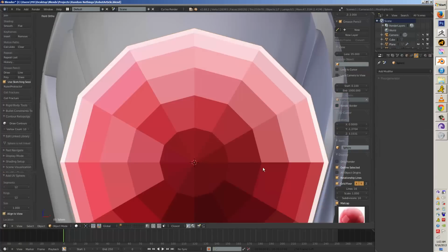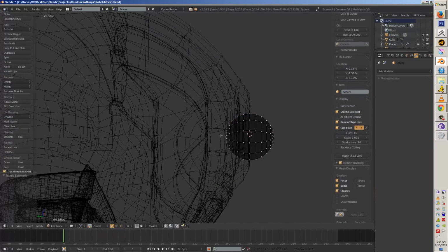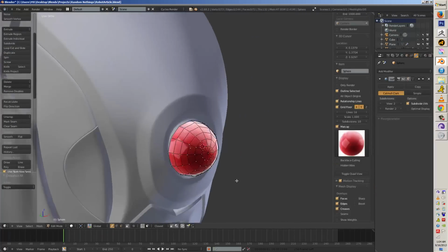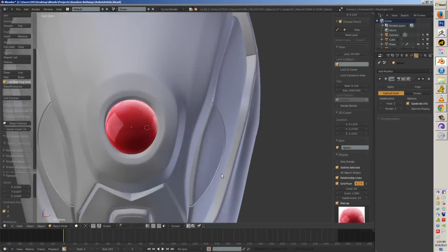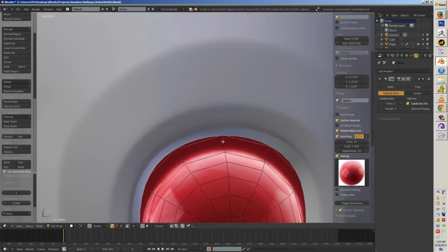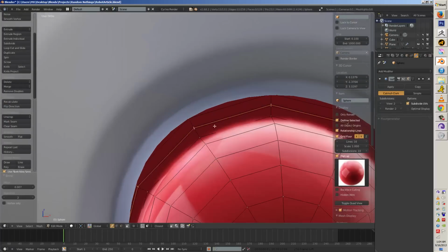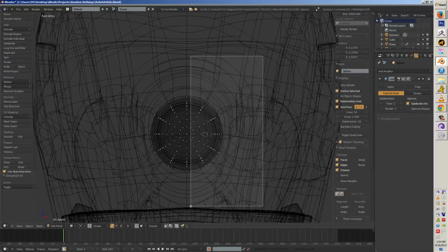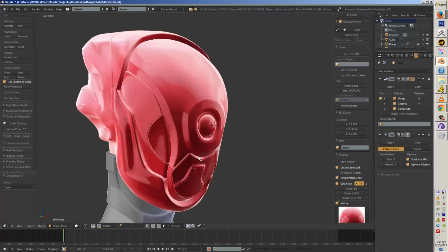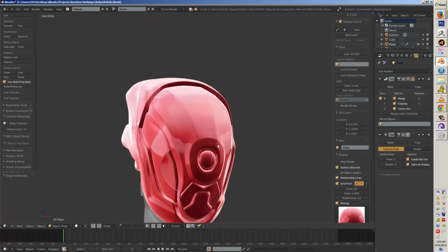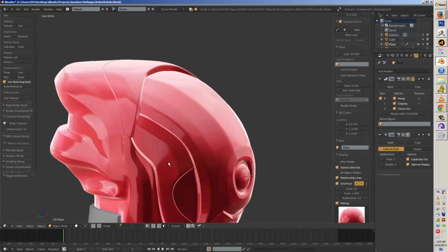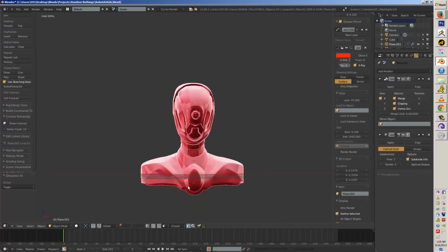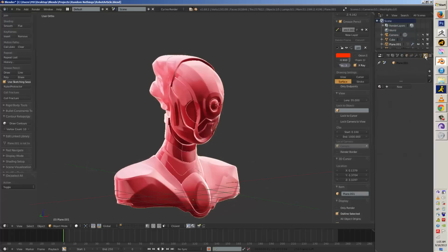So now comes the part to fill in the center. Bring in a sphere, face it in the front. For the longest time, I used to manually turn those edge poles into quad faces, but now I've realized you can select a 12 span polysphere and just press Alt J, and that'll actually let you set it to be all quads without a whole lot of work. However, I've noticed on some of the larger numbers, the calculation doesn't always create even quads as you would want.